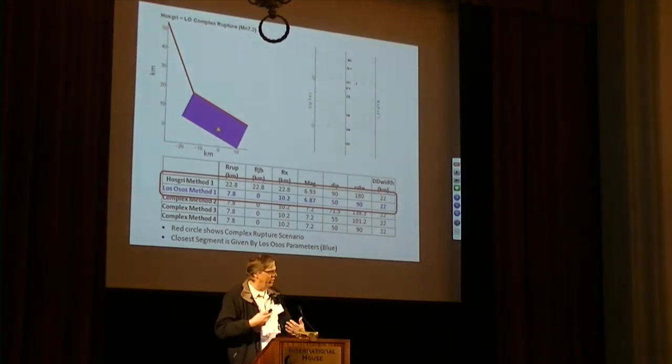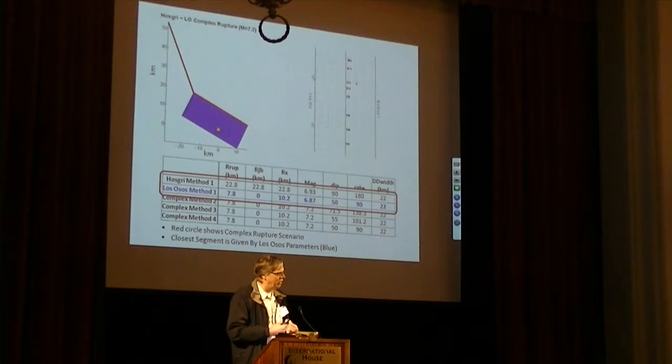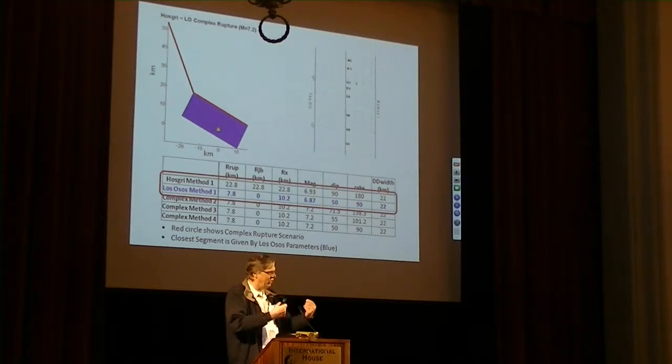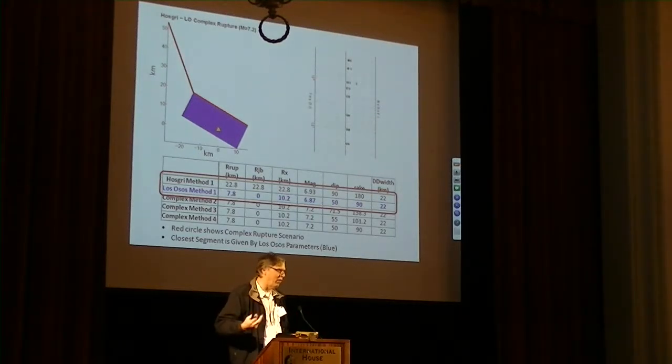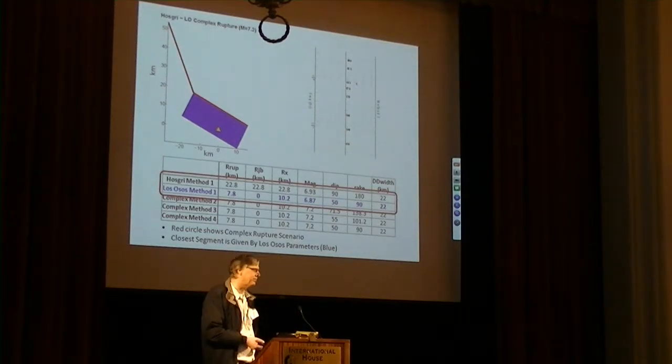And so when they did the simulations, they did a simulation for this piece, a simulation then for the strike slip part, the simulation for the reverse part, and then added them together in the time domain. Okay, and SRSSing is similar to that. It's not surprising that that works because it's the same basic concept that we're adding in the time domain where they're overlapping with their strong shaking. So this is an easy rule that we can use in the hazard calculation.